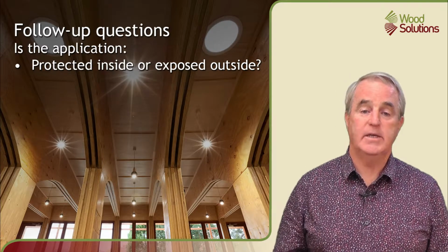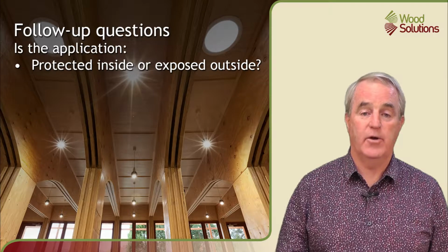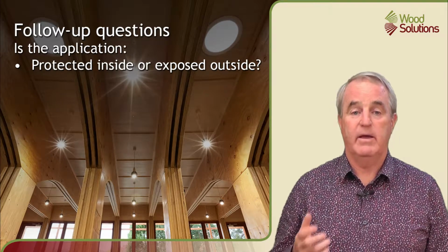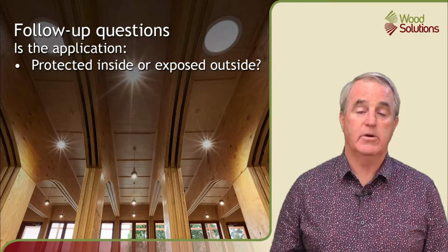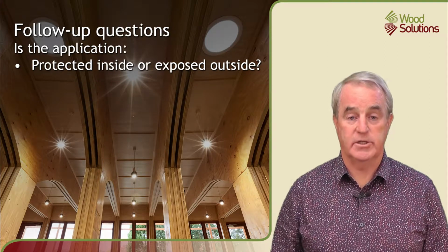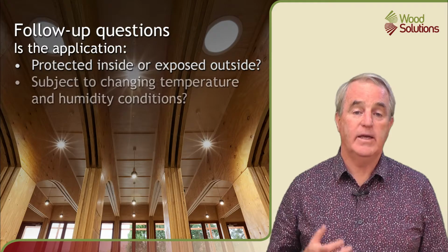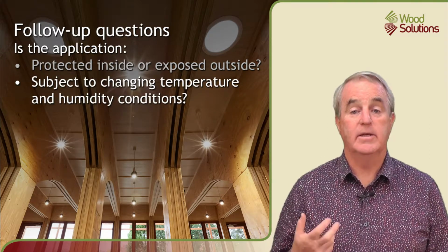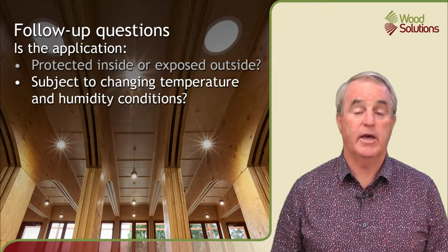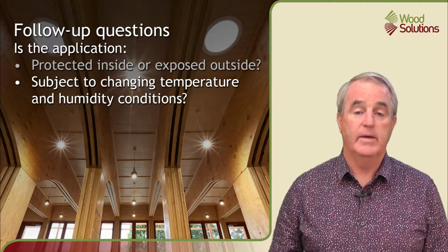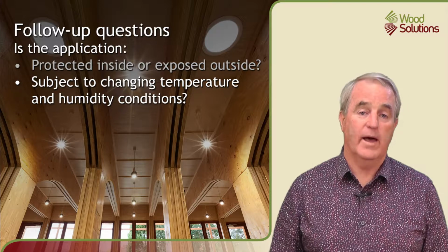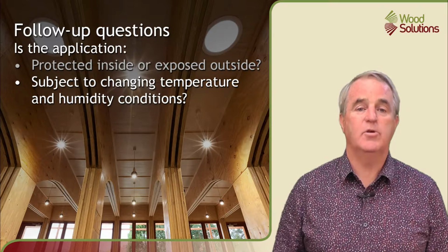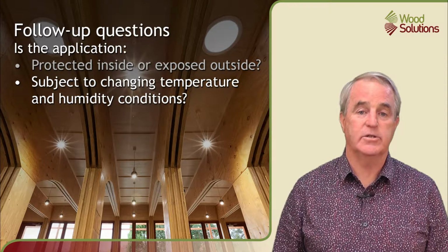The first is, is the application protected inside or exposed outside? If it is outside, durability will be important, as will the material's response to changing moisture conditions. Then, is the application location subject to changing temperature and humidity conditions? Spaces with high humidity, such as pool enclosures or with large heaters, pose particular moisture content and installation issues for many wood products.